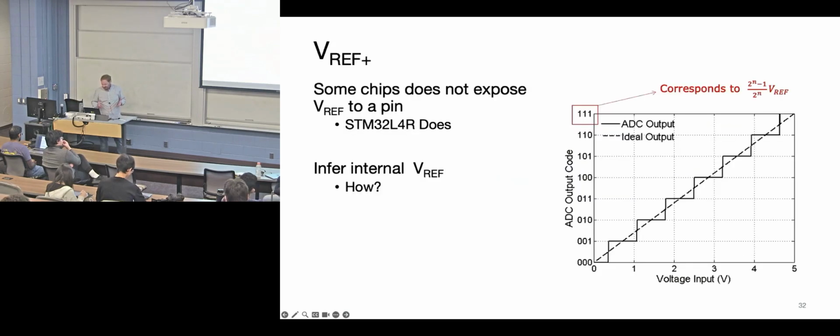Lastly, to wrap up, there's a lot of it. It's not exactly what I think is important to teach anymore. Well, I did already say this. So knowing where these VREFs come from, where the internal ref comes from, and how it's going to change this value, this scale is important. In your world, most of the things are going to be from 0 to 3.3 instead of 5, because that's the reference, or the power supply voltage, for your ADC. But it may need to be 2.8 or whatever the reference voltage is.